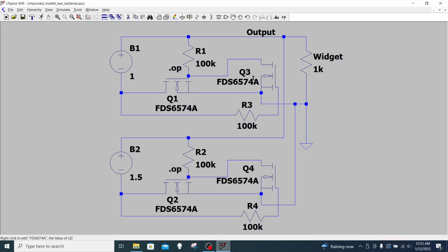So this more complicated MOSFET rectifier circuit serves us well in a lot of cases. It may be a good practical solution. When fresh batteries are installed correctly in the device when it's about to be put in service, it may be that the battery life will be slightly longer in this case than with the Schottky rectifiers.